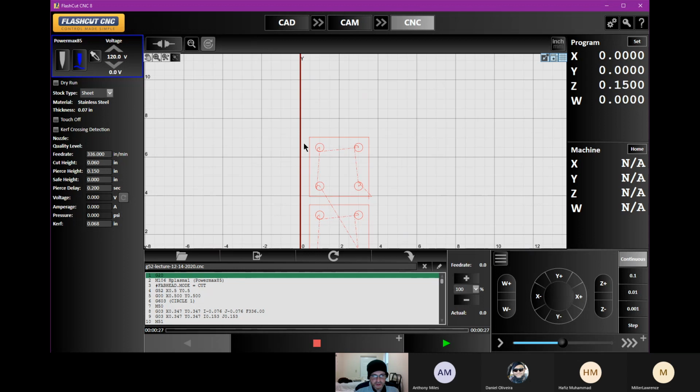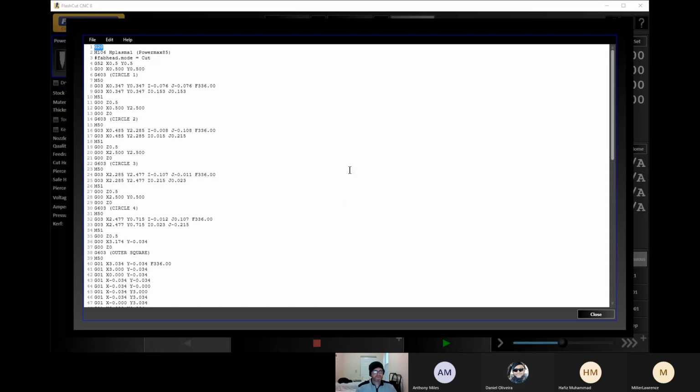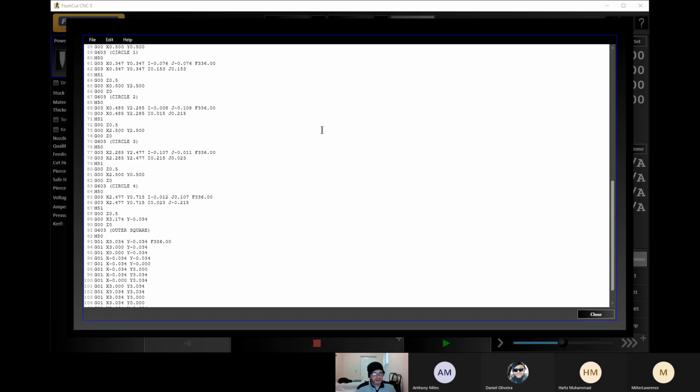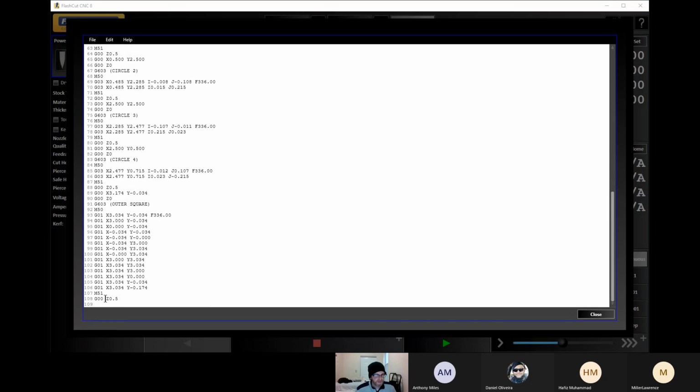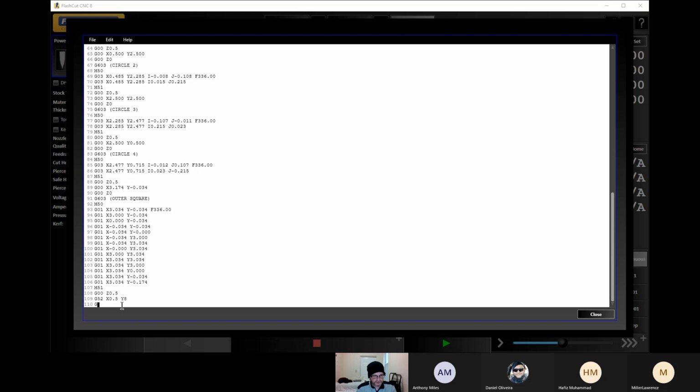So our next position, we'll stick with X 0.5, and we'll go with Y8. So we go back into our editor, scroll all the way down. We put in a G52, put in X 0.5, Y8. We bring our torch back down to the 0 position.